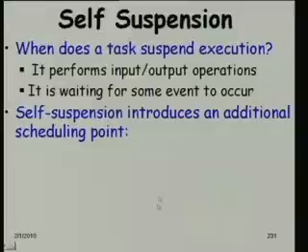One is when a task arrives, the scheduler needs to check whether it is a higher priority task than the currently running one and whether it should be scheduled. And the second is when a task completes, it will check which is the highest priority now and take that up for execution.